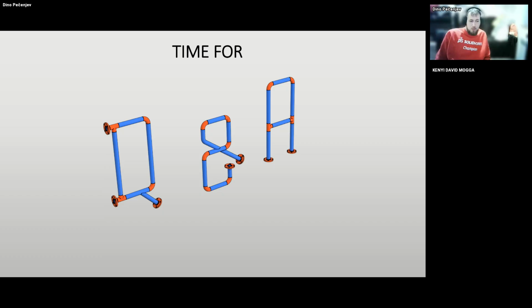Regarding the flow, you just need to close the starts and the ends, so it doesn't have any holes, so you have closed volumes. But yes, flow simulation can be used with routing. That means if you want to use, let's say, HVAC for routing and then use the HVAC simulation for flow, you can do it.